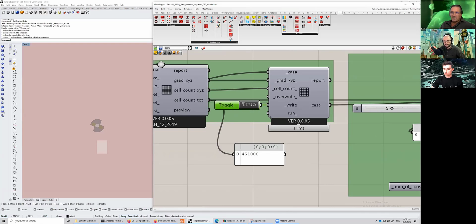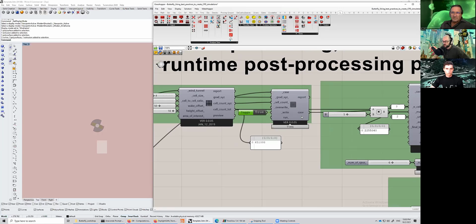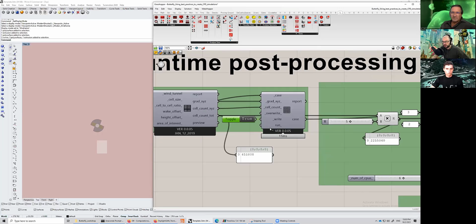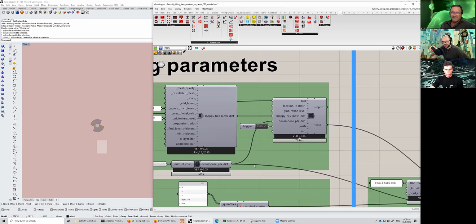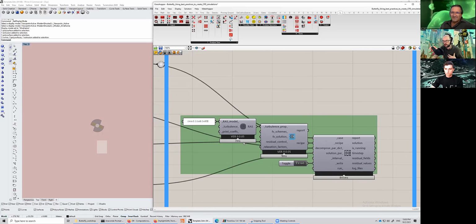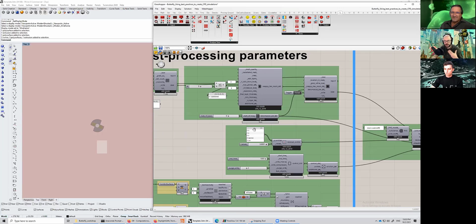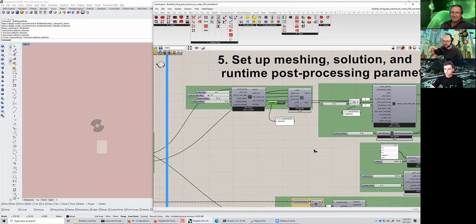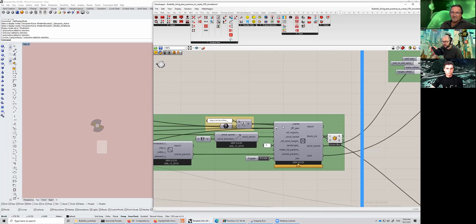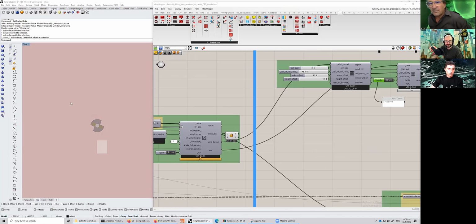If you put it here, something will pop up and it will create a block mesh for you, the blueCFD that we said to install, that we will show you how to install. And if you do it here, this will take maybe a couple of minutes, the meshing will take maybe a couple of hours, right? And the other will take a couple of days. So I won't do it because personally, I run them differently. And I also wanted to show you what Butterfly creates. So in this 6.5 seconds, and the rest were milliseconds, let's see what we created, right?